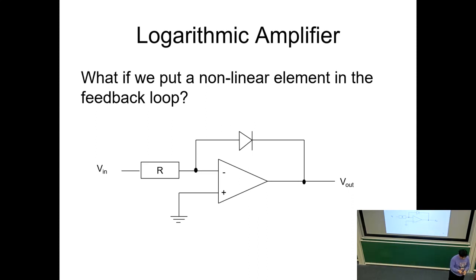About the adder, I built this circuit and simulated it. I found that if I don't have an op amp, the signal still sort of sums, but you won't get any gain. You won't get any amplification, and you've got all kinds of loading effects. What you've done is only look at two voltages on the oscilloscope, which has a very high input impedance anyway. If you then use that signal in some other circuit without a buffer, it's just going to go wrong.